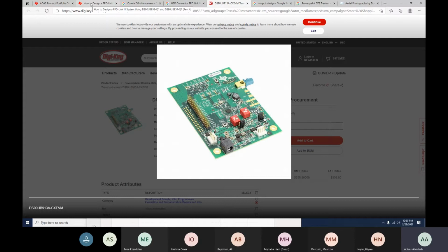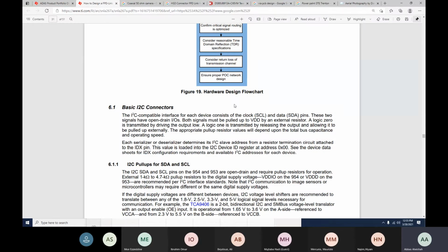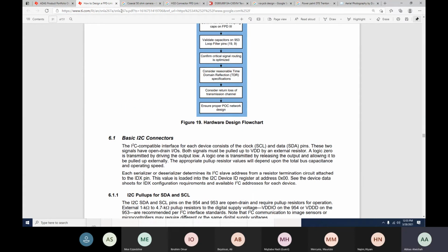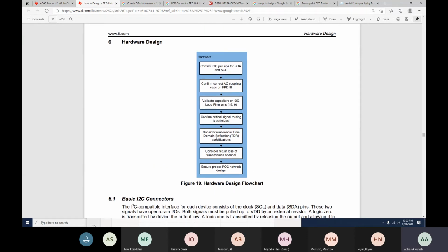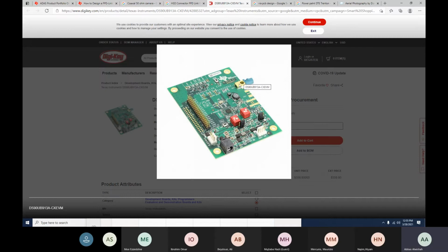If it's not, you're going to have data that's not matched, because the internal filter in the hardware is set up such that it's looking for specific values. On your connectors here, it's looking for a specific value. So if you have a value that goes outside of the filter spec, it's no longer recognized, and it's a data packet that has been missed.